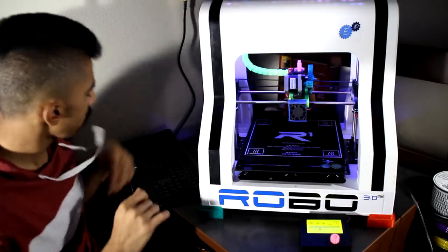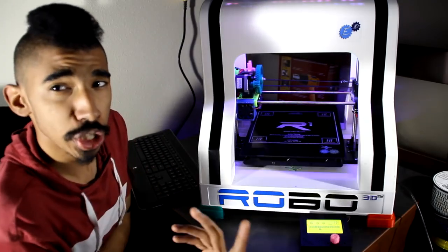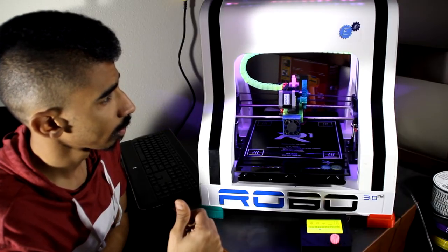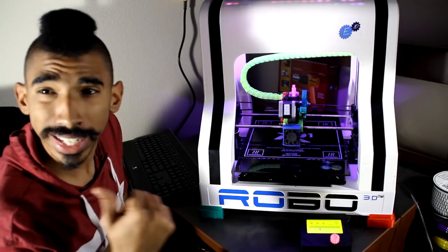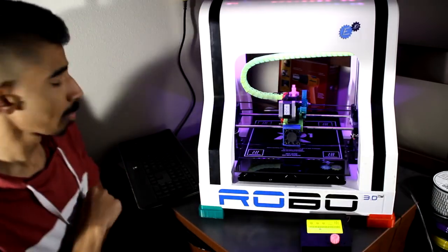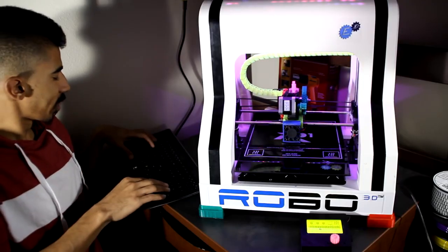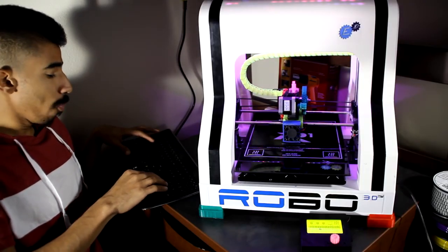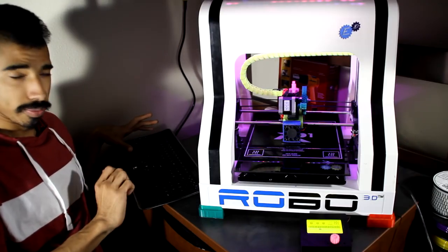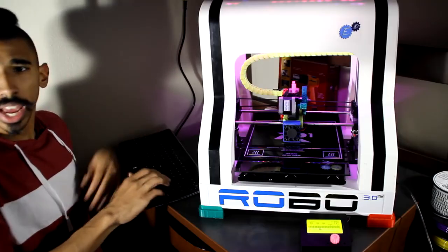But while it's heating, I can still run other commands like a G28. Which means I can still home, I can move, I can auto bed probe, I can do the whole shebang. But if I do this, I raise the Z-axis by 10, I'm going to do an M109 S220. And then I'm going to do a G28. And then I'm going to do a G29.